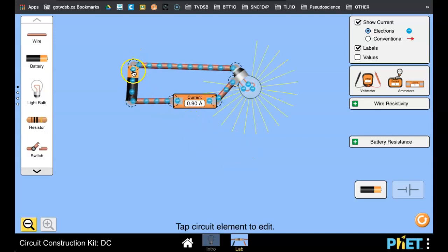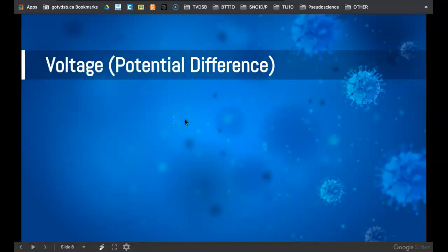And so you can see the electrons come out of the battery, they go through the ammeter, so it's connected in series, and then go to the light bulb and then back. But you'll notice putting this in there didn't change anything about the circuit, right? The light bulb still stayed on, the flow of electrons was still the same. All this is doing is counting. That's it.